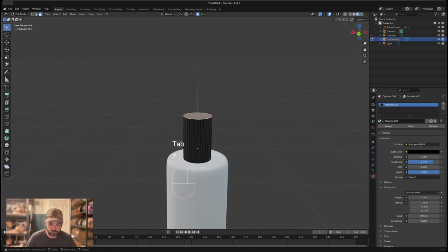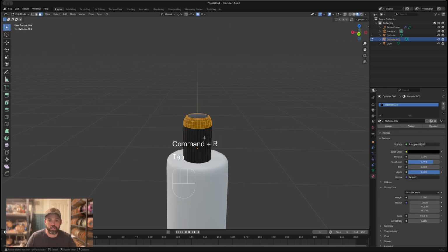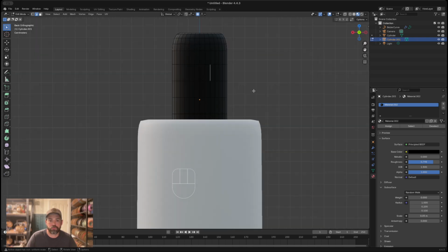For one, I'm going to go back in and I'm going to add a bevel here, and there we go with Command B, and right click and Shade Smooth. If you were to go into edit mode and hit Command R or Control R for Windows, it allows you to add new horizontal line segments across this wick, and I want to add a decent amount. Okay, and then once I've left clicked, I can move those into different locations. So now I have more horizontal lines on this wick.